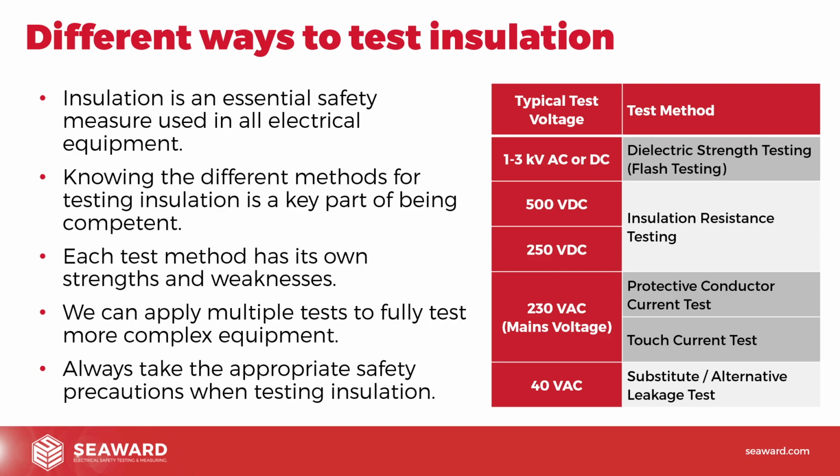And then we carry out the measurement, very similar to protective conductor or touch current tests, and then we scale those readings up to what we would have got if we had applied mains voltage to it in the first place. So again, this is a very safe, soft test that we carry out. But we need to be aware of the different options that are available.